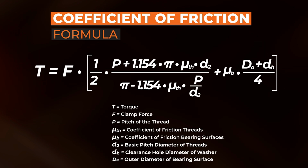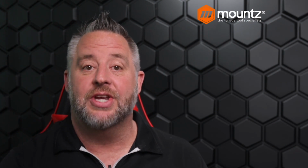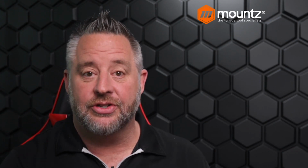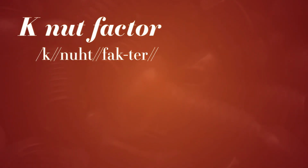Now, this being a little bit confusing, fastener manufacturers have come up with what would be a constant or a theoretical value for their fasteners as it relates to torque, and that would be considered a K-nut factor.